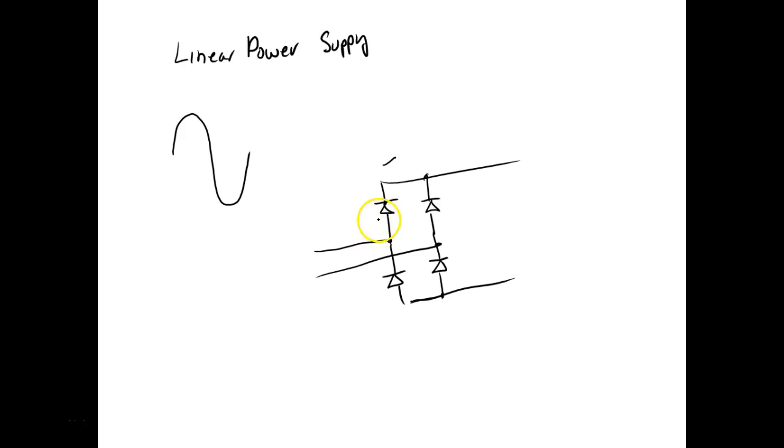Okay. So anytime you forward bias these things, or make them work, they act like check valves. Have you ever heard of a check valve? You're going to run into them. We use them in fluid power. We use them in electronics. A check valve is a device that only lets something flow in one direction and blocks it in the other direction.